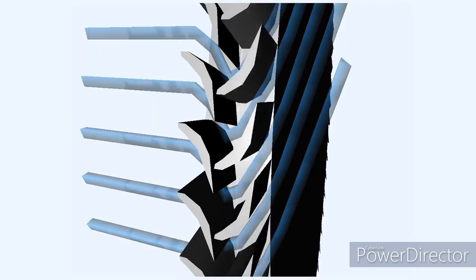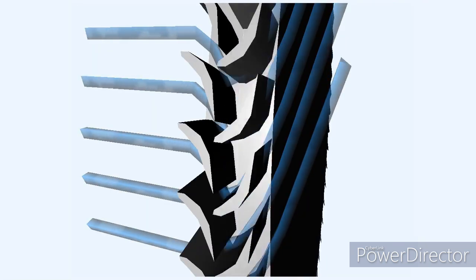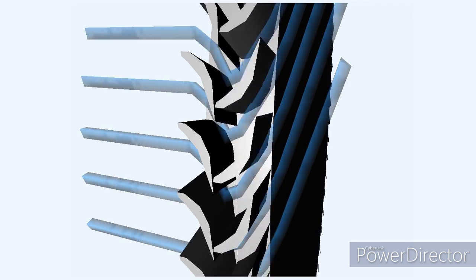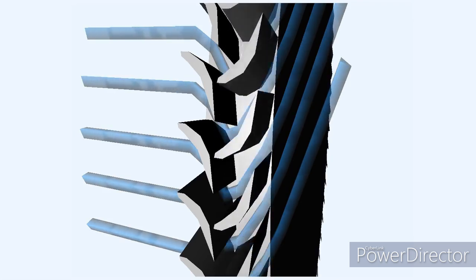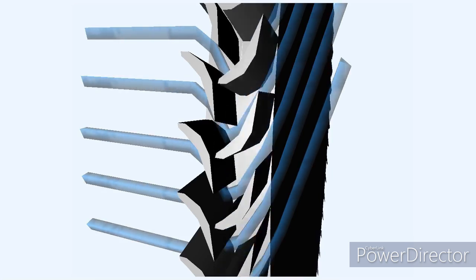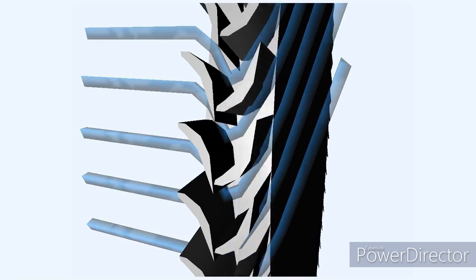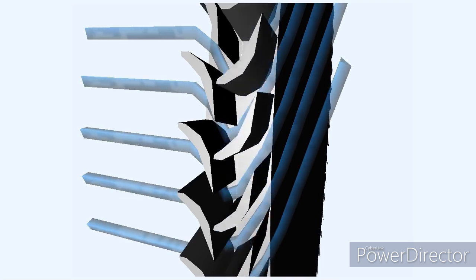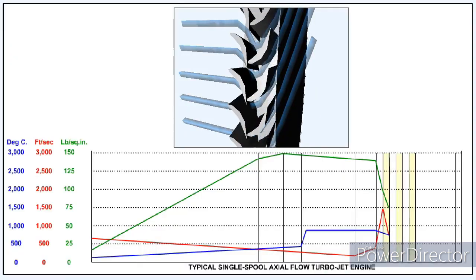The torque which is applied to the turbine blade is dependent, amongst other things, upon the rate of gas flow into it. It follows, then, that the faster we can make the gas flow into the turbine, the more torque we can transfer to the turbine. Logically, therefore, if we convert some of the considerable pressure energy of the gas stream into kinetic energy, it will be more efficient in imparting a turning effect upon the turbine and its shaft.